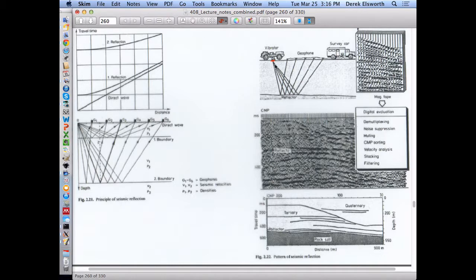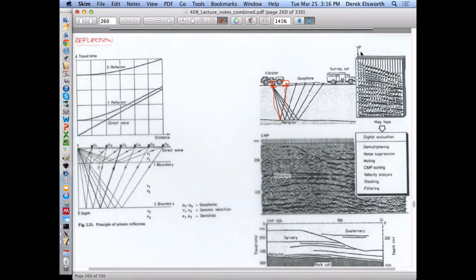It puts in some kind of harmonic excitation, and again you're measuring the travel time between initiation and recovering it at the surface in a geophone. It's really not very different from the transmission and receiver idea for GPR, often plotted as a trace. If you look at these signals, this would be location in the x direction for your geophones.